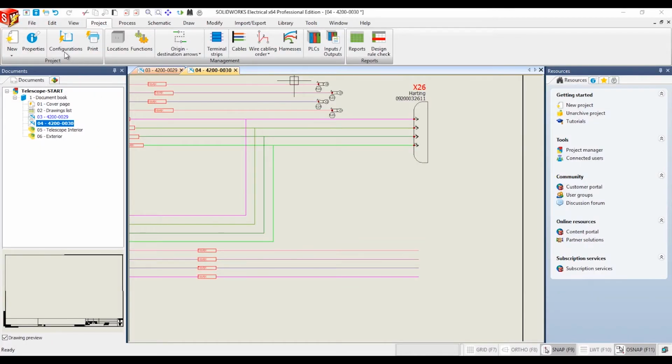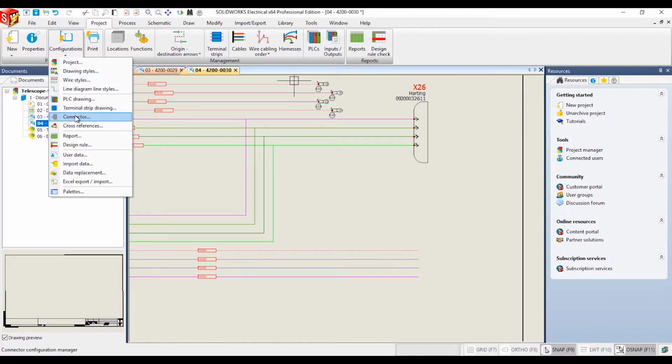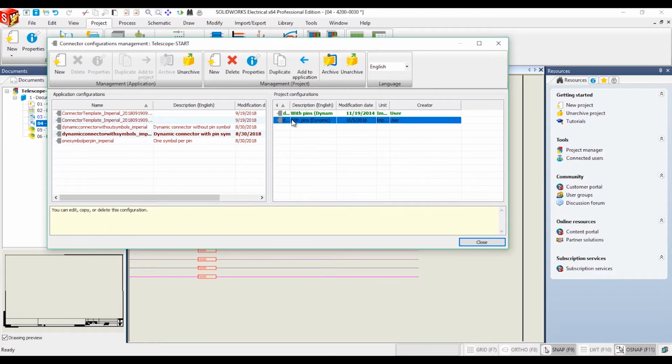Our next set of enhancements are my personal favorite because they came directly from a customer's request. New configuration and insertion have been introduced to improve the process and flexibility of inserting dynamic connectors in the schematic drawings. The connector configuration has expanded the parameters available with additional dimension options to help create the exact size and shape of the connector we desire. A few new choices we can see are to include corner radius value and pin side.